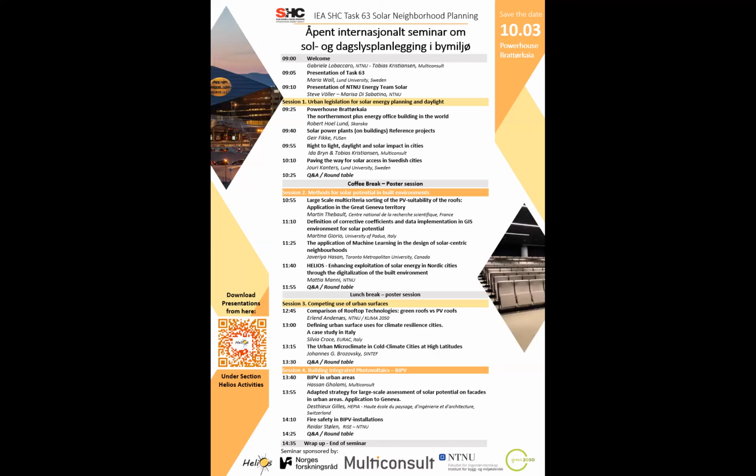So, yeah, it takes just a small amount of combustible material in that cavity to make a fire propagate. But of course, if you can keep it at zero, then you wouldn't have that problem. Just for glass BIPV, normally we have really high fire safety for the BIPV system. I know that, but for glass backsheets, not that much.